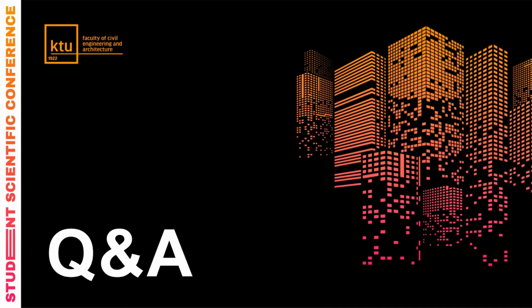I think for now, it may be difficult to get the amount of carbon dioxide we need for this. Also, I think it could now only work for small units, for example, masonry units or other samples that are made in factories. So we can't carbonate poured, on-site poured concrete, just what is made in the factory.